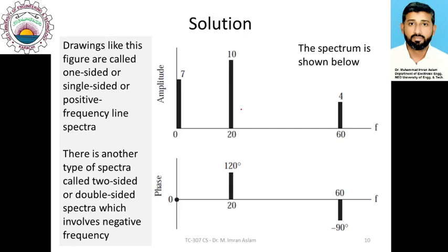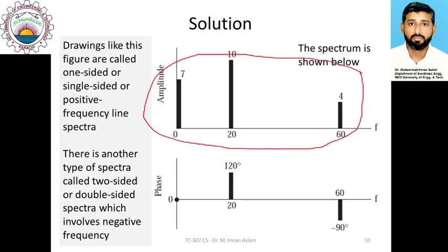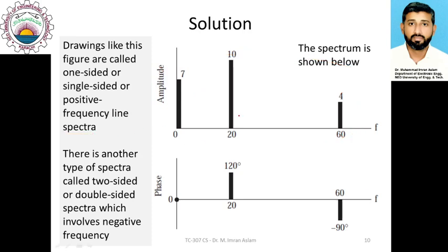At this stage I want to mention one more thing. You can see that the overall function was periodic. The overall spectrum appears in the form of lines. So we see 3 lines in the amplitude spectrum here, and we see 3 lines for the phase spectrum here. So generally the spectrum appears as lines. It's named a line spectrum. And you must know that for all periodic functions, whenever we plot their spectra, the spectrum generally appears to be a line spectrum.